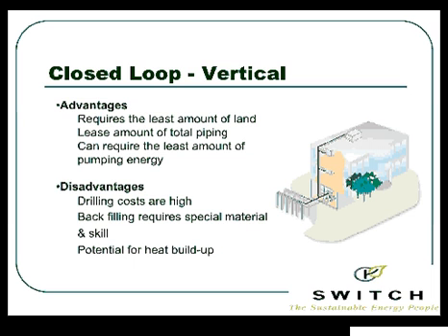Issues, though: drilling costs are high, typically. And again, as I stated on Tuesday, that's a factor. Are we drilling into sand? Are we drilling into rock? Are we drilling into clay? Those are those variables that are going to be site-specific to your home. Backfilling requires special material and skill, right? We have to backfill with the appropriate materials because we might need to dig it up later. Hopefully not, right? And we obviously don't want to damage the pieces of pipe we just laid in the ground.